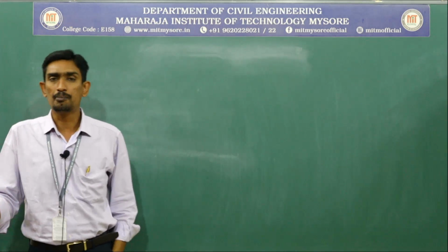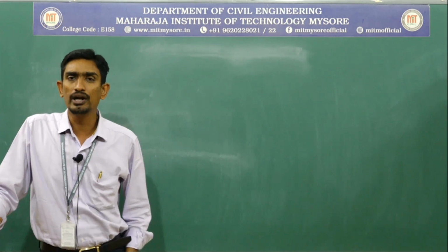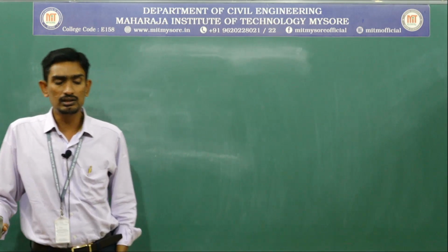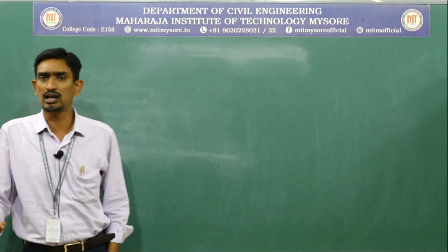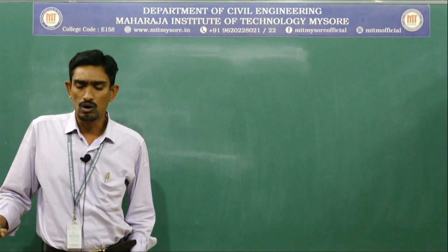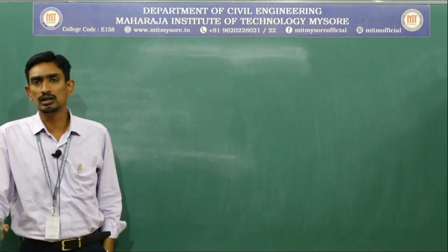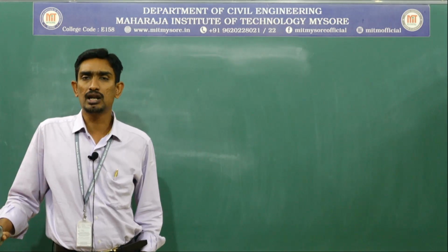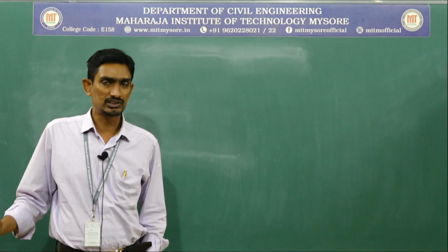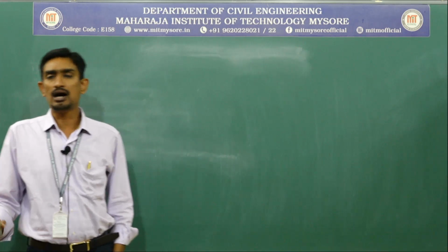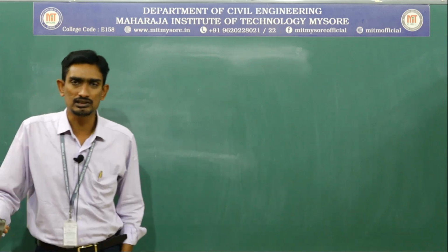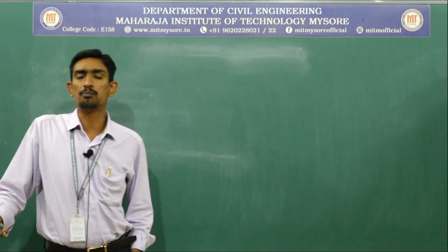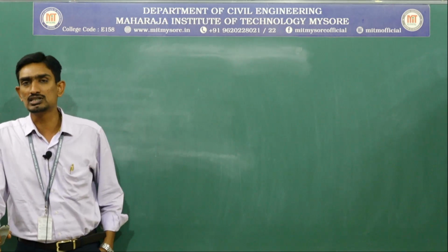This is also a pozzolanic material which I can use as a best replacing material. But the predominantly used pozzolanic material is fly ash. In the market, whatever cement you obtain is PPC, Portland pozzolana cement. In this, the predominant pozzolanic material is fly ash. Is it clear? Apart from this, as I mentioned in the last session, there is ground granulated blast furnace slag, which is obtained from the iron ore industry, that is in the Jindal.